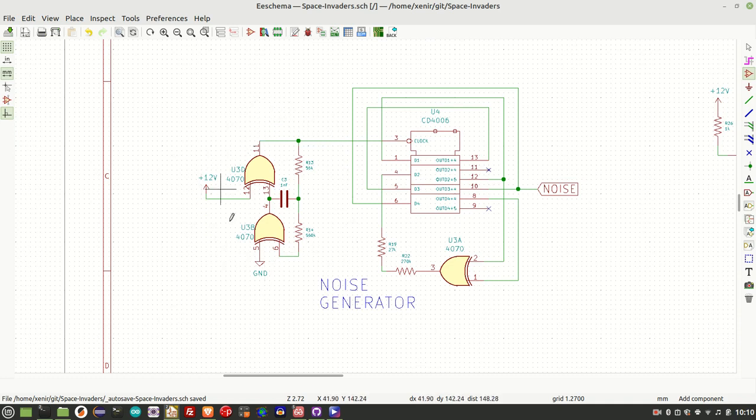It's an interesting little oscillator circuit here, and basically what happens is this is held high, this is held low, and then to start with, this basically is high, which charges up this capacitor through this path here and then through to ground. As the voltage right here rises, ultimately it turns on this XOR gate here, and then when that happens, the cycle reverses.